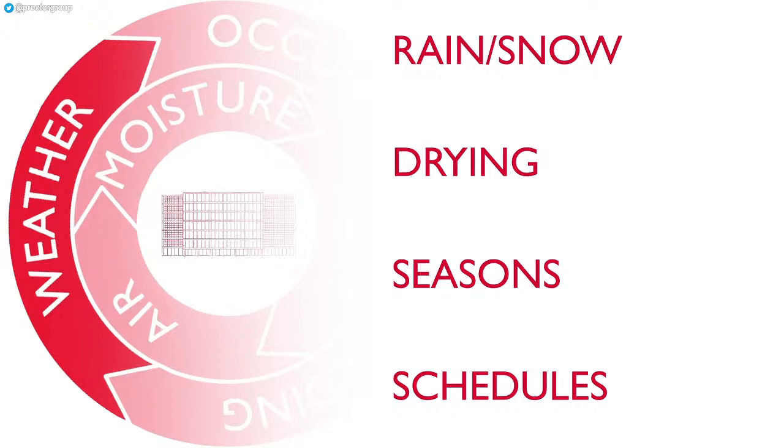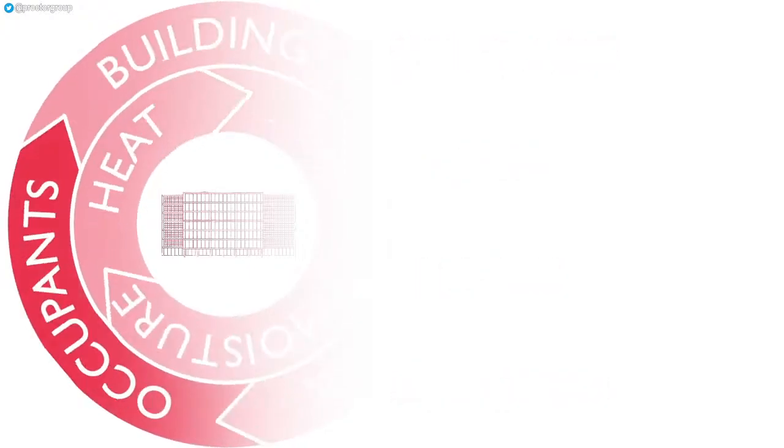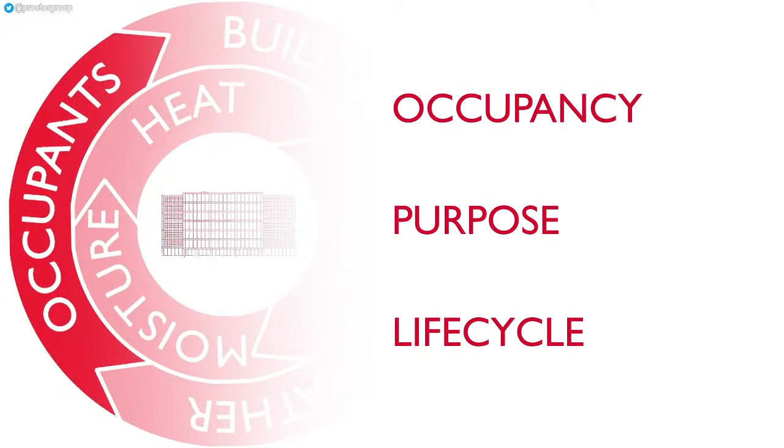Being weathertight earlier in the construction process and generally being composed of drier materials, off-site construction has an important advantage hygrothermally. By reducing the initial moisture loading on the building fabric, the design can be more precisely tailored to manage moisture associated with the occupants of the building and the uses the building will be put to, leading in turn to a more efficient fabric envelope and building system.